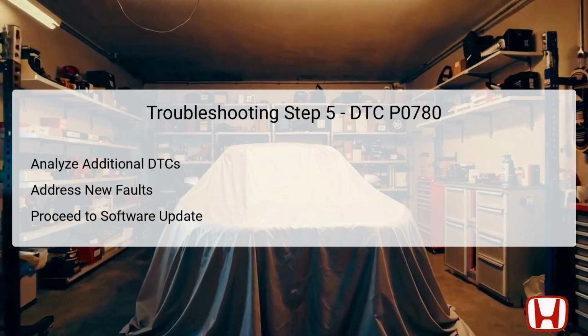The final troubleshooting step requires the technician to analyze any additional DTCs that were identified alongside DTC P0780. If any new fault codes are present, the technician must duplicate the failure and proceed with the diagnostic process specific to those codes. For example, if DTCs P1898 or P1899 are indicated, these will need attention as they are closely related.